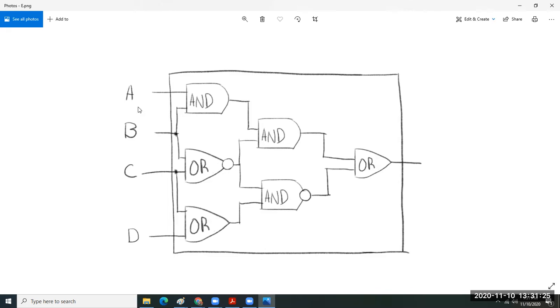Yeah. So how large is the truth table for this one? A, B, C, and D. 16 inputs. 16 possibilities with the 4 inputs, yes. And so you'd have a W1, a W2, which would also be the W2 here. So the tricky part for this, when this wire is split, so the external C is split. So when you're doing your HDL, that big C is going to be in both of those statements for this OR and this OR. Same with the B, it splits. So the large B is going to be in the HDL statements and the parts statement for this and this OR. Everybody knows what I mean when I say that, yes? Kind of, sort of? Like if you had little a, little b, little a, little b. Kind of. Kind of, okay.